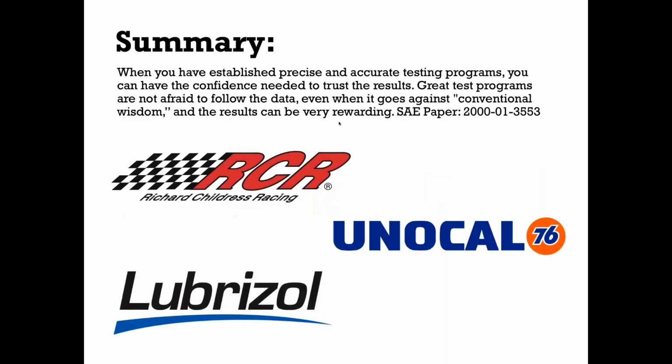And then, another example is, and if you've got time, especially if you have access to SAE papers, look at the SAE paper number up there. A good story is this. Back before Gibbs even did business with Lubrizol, Lubrizol and RCR and Unocal were working together because Lubrizol was doing all their testing using passenger car engines. And they came up with this whiz-bang triple detergent formula that had magnesium, sodium, and calcium detergents all in the same oil. And on all the industry tests for passenger cars, the stuff is phenomenal.